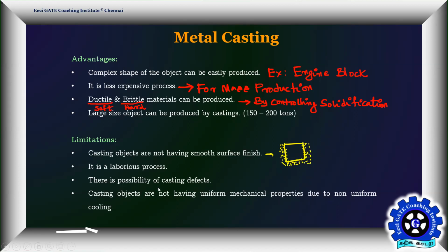Next, there is a possibility of casting defects, obviously, because you're dealing with liquid metals. If you make a small mistake, a small mistake is enough. What will happen? Some air particles will be trapped inside the casting, or sometimes your liquid metal will be interacting with the environment, right? And oxygen is a very bad player in this, because every liquid metal tends to have oxygen attack it, and it will oxidize, and that will make your product very defective. You don't want that to happen, so you have to make sure that oxygen is not interacting with this.